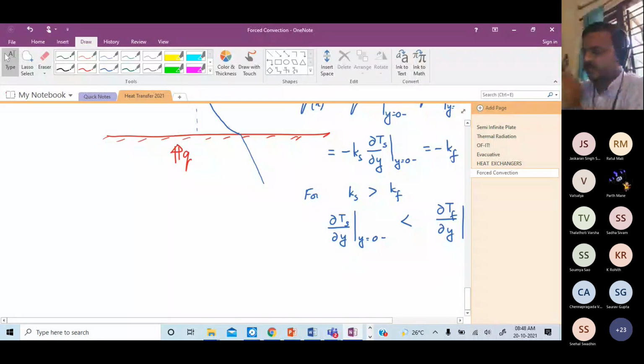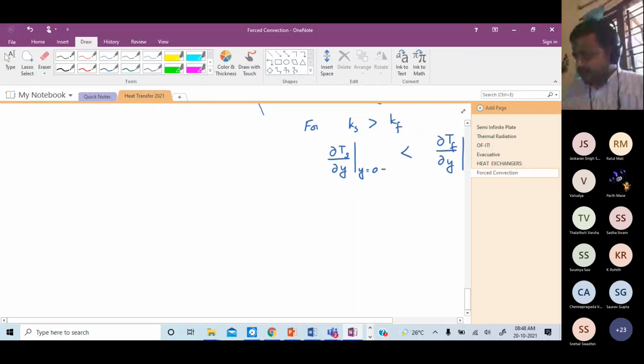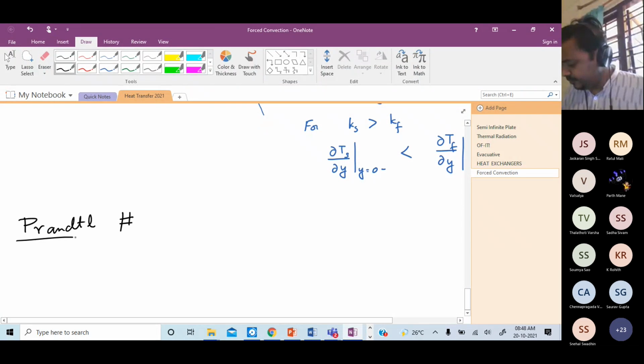So we spent a little bit of time on the Nusselt number, but that's okay, because that is the central concept. Next, I'll go fast now. The Prandtl number is the second one. What is the Prandtl number? It's a fluid property, number one. Completely a fluid property, with no dependence either on geometry or on the flow.